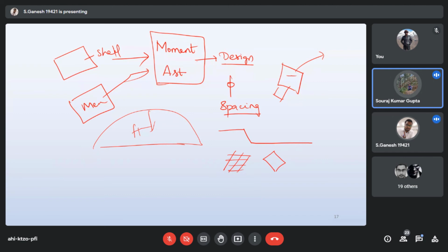If you convert that to a membrane, you might have a chance to save your AST values, if I'm not wrong, because I also worked in ETABS. Thin shell, we can do it, no wrong in that. You can go for thin shell, but consider the economical aspect, as in AST values. So membrane can be much better for normal slabs, like G+4, G+5.